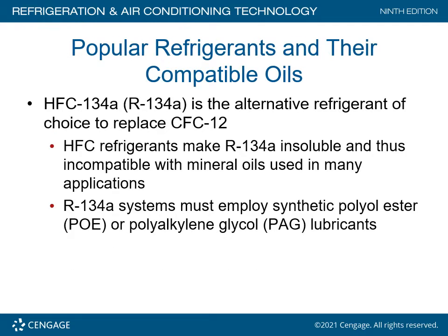Popular refrigerants and their compatible oils. HFC-134a is an alternative refrigerant of choice to replace CFC-12, which is in widespread use. HFC refrigerants, including 134a, are insoluble, thus they are incompatible with mineral oils used in many applications.